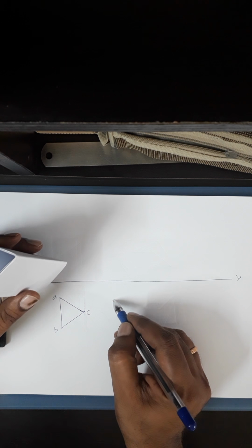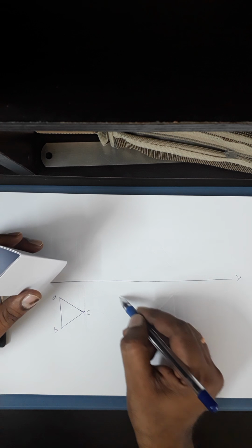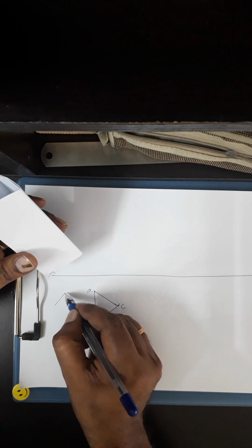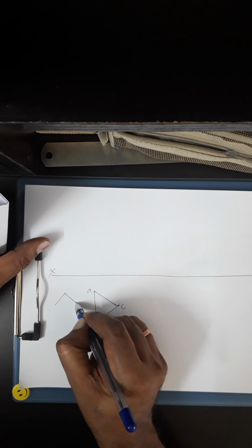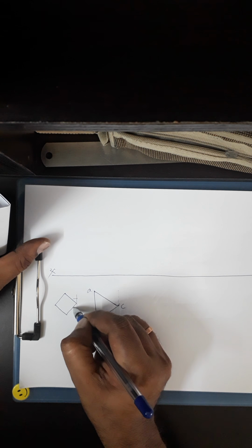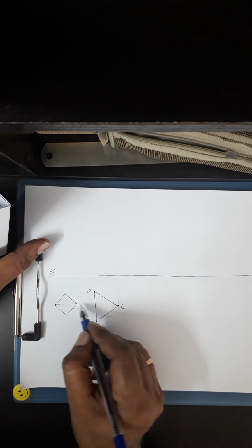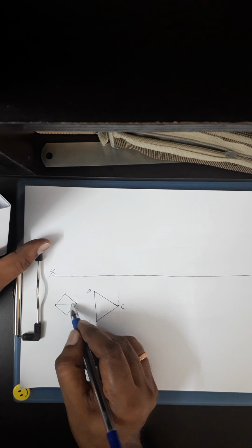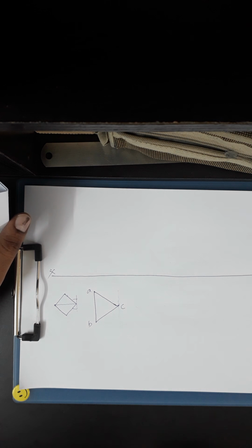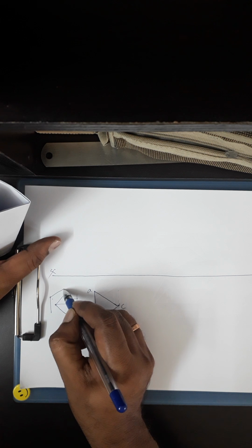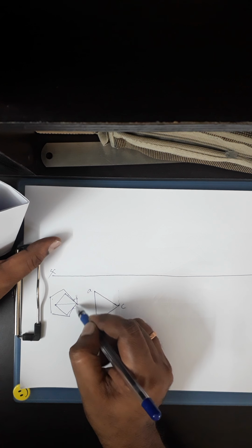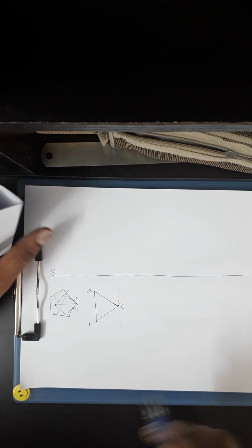It's a square prism, you have to draw a square prism, something like this. I'll just draw it for you here. Draw this square in such a way that, if I assume a line here, that should make equal inclination. In that case, I should draw a diagonal parallel to the XY line, so that these two will be at 45, 45, because in that case, even this makes an equal inclination with the vertical line. The same I can construct even for a pentagon, so having that corner, the edges containing the corner should make equal inclination. That way I have to draw this view.